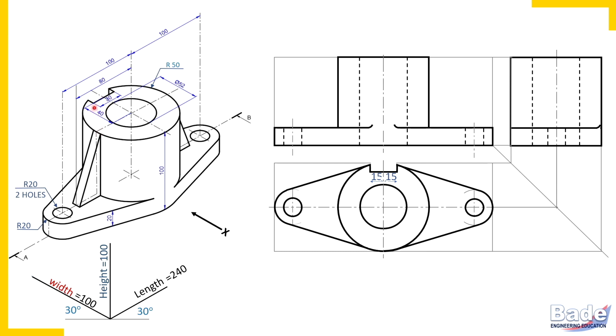From all these four corners there are vertical edges, and when depth is not given, it is assumed a through slot. So you should get a dotted rectangle from top to bottom. So any hole like this hole: in top view opening, in front view rectangle. Similarly slot also: in the top view opening, in front view rectangle, in side view rectangle.